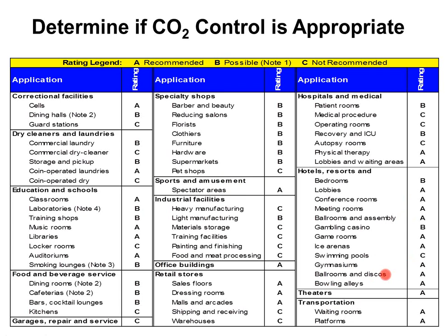The ones that are really bad either have some kind of chemical thing going on, or they don't have people coming and going, right? So a guard station at a prison, people really shouldn't be leaving that unoccupied, right? It's always supposed to be fully occupied with guards, so that's not a good candidate, right? Commercial dry cleaners, we're not ventilating that space because of the two guys breathing back there. We're ventilating it because of all the chemicals that they have to inhale. So whether there's one or two guys in the back, it shouldn't make a difference on my ventilation rate, all right?